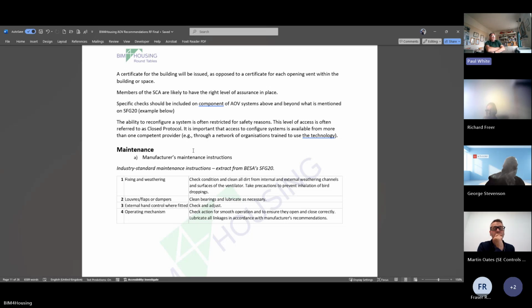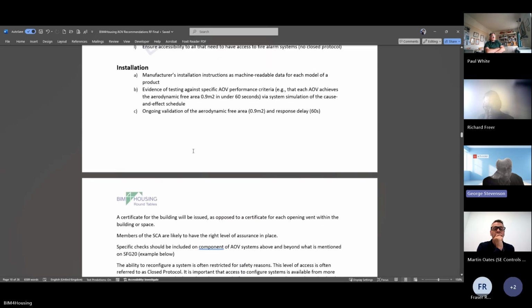and then you have the installation schedule where they install it and they take some photographs, particularly where there's anything that will be hidden during the installation. And then they give their agreement that they've installed it correctly against the design selection. Okay. Jess, can you scroll up a little, because you're missing the bit that Richard, yeah, that's it. So you're looking for evidence that the installation has been carried out against the manufacturer's instructions.